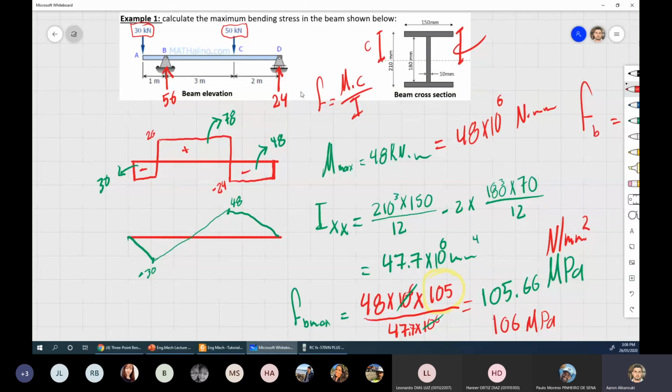can anyone of you tell me that when the manufacturer made this steel beam, they made it 100% accurate, with that strength of steel all over the beam? There are some areas where, with heat, we agreed this would be melted down to be able to be formed to this shape. When they heat it up and then cool it down, these particles of steel maintain what we call residual stresses. They stay too hot in the center here.